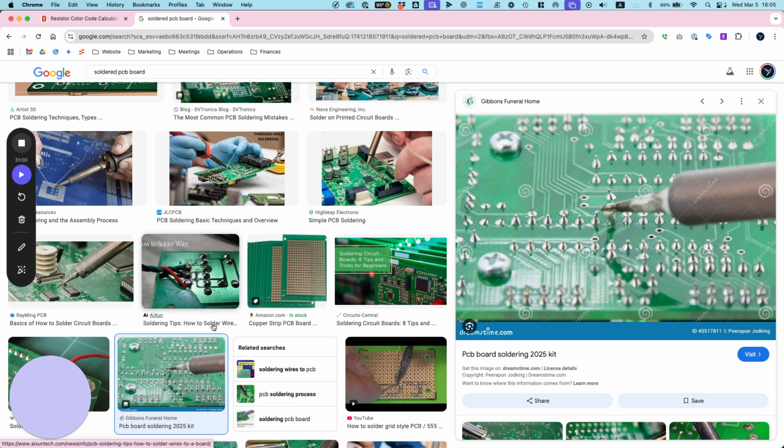All right, let's check the actual resistance here. If we're too lazy to look at the colors, let's see what we get here. What do we see? What is it? 388.5. Oh, that's pretty close to our 390. Actually, I would say it's within plus or minus 1%. Well, that was just one particular resistor. I don't know about the rest of them.